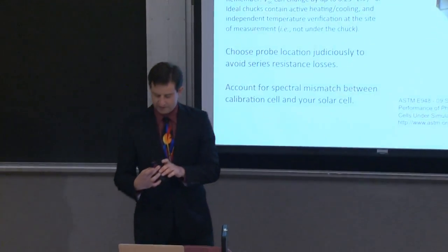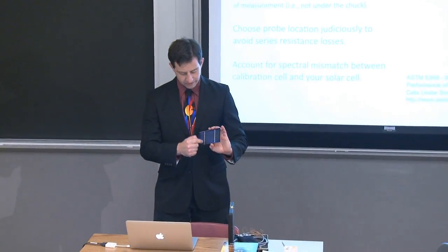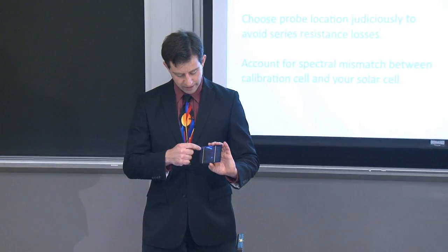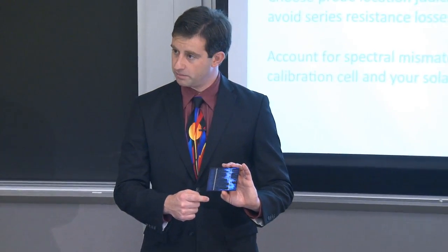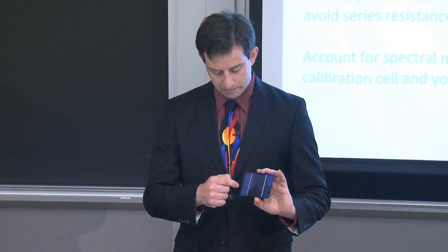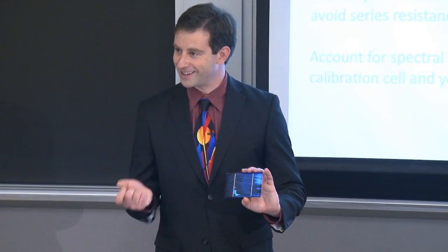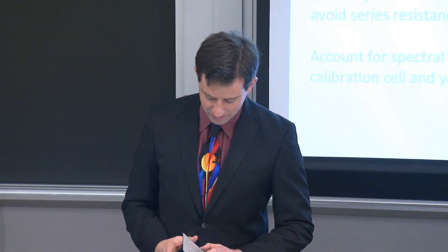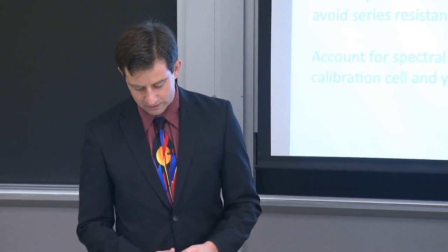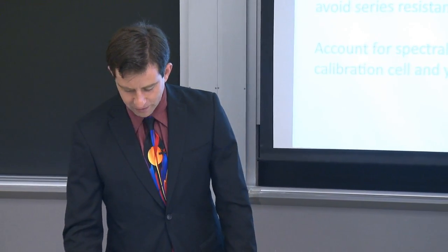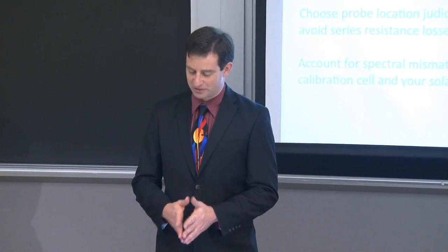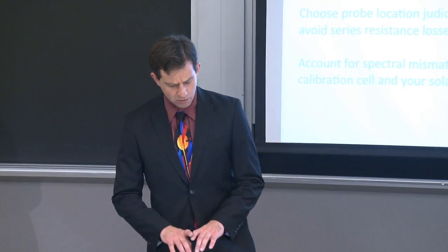Typically on these devices in a module, you'll have soldered contacts in the front, and so they make contact with the entire bus bar, but really, depending on your soldering machine, only in a few locations where there's really a good electrical contact, and on the back in 3 locations. So yes, there are differences in how the cell is contacted in real life. Could be one of the reasons for discrepancies between module and cell efficiency, albeit probably one of the minor ones compared to inhomogeneities.